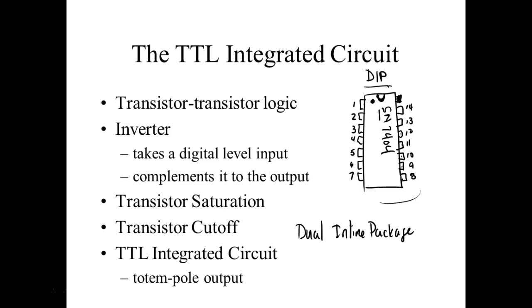Top left, start with that first one. That would be pin number one. The pins are not going to be numbered because they figure you know how to number them, right? But you don't go down and then go over and go down. It goes down, then comes around and numbers back up, no matter what size they are. The biggest package they ever came out with was a 64-pin package, which was 32 pins down one side and 32 pins down the other. It numbers the same way. Find the notch, look at it from the top. We okay? So which one would be the top?